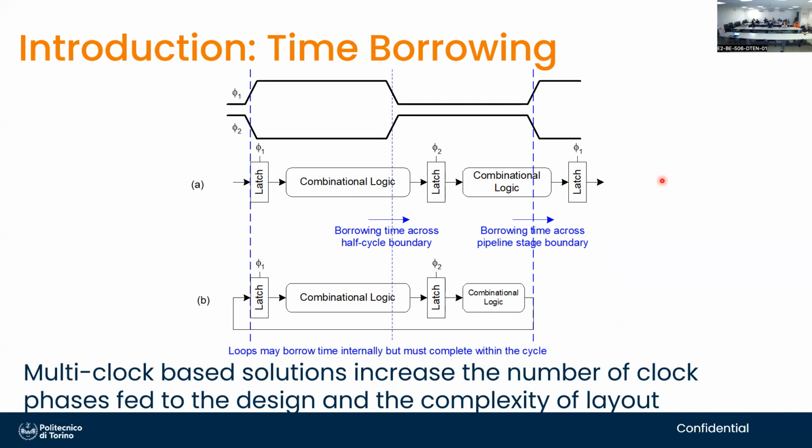Sending the same clock edge so that it arrives at the same time to all the flops in the circuit is very difficult. Getting to do the same with two is not twice, it's probably 4 or 8 times as difficult, which means in practice, except for old times when people could spend months and years designing circuits with 10, 20, 30 flops, now the dominant design methodology is based on flip-flops, not on latches.